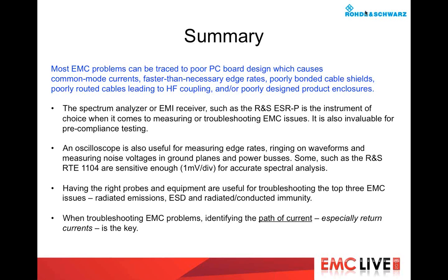These instruments are also really handy for pre-compliance testing, and I have set up 3-meter measurement sites in conference rooms, in basements, and office cubicles. And yes, you have to deal with ambient signals from radio and TV and so forth, but if you know the major harmonic emissions, you can zero in on just those and ignore the ambience usually.